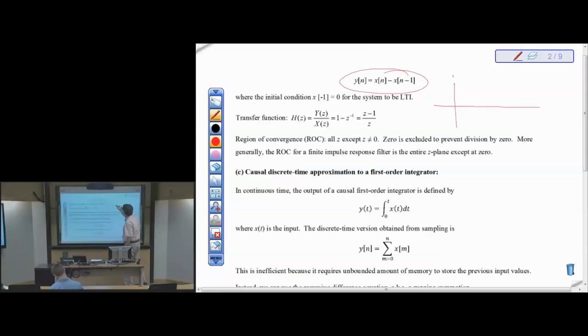So if I have a discrete-time signal that alternates between 1 and minus 1, that's as fast of an alternation as I can get in discrete time. And this signal is minus 1 to the n, which is cosine what? Cosine what n is that? Yep. So minus 1 to the n is cosine pi n. That's the highest frequency possible that we can capture.